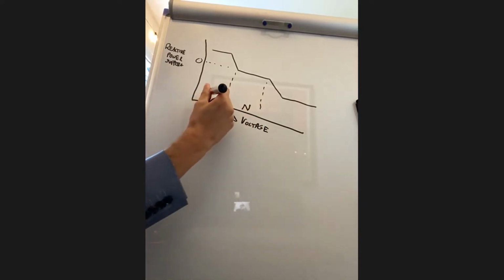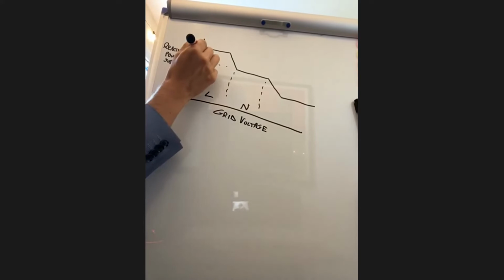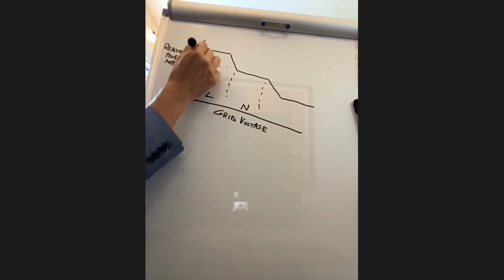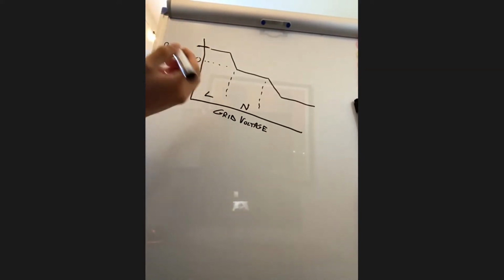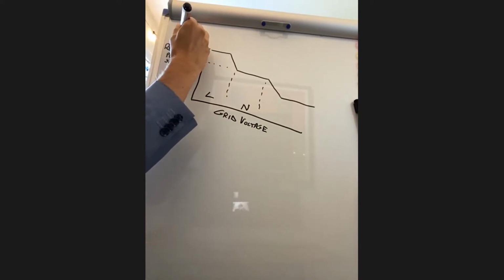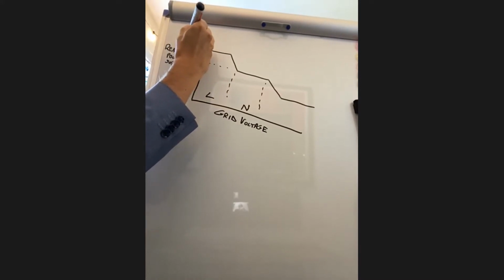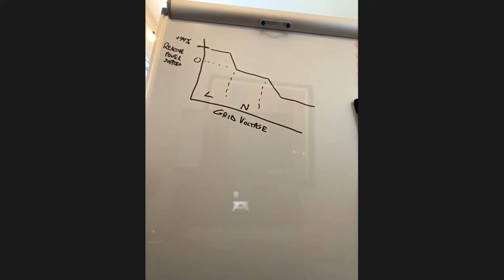However, when grid voltage is low, you could say, actually, now I do need you to give me some reactive power. So give me, let's say, plus 44%, and I can show you where that number comes from, but it's just a relatively common number that you might use in a volt var curve. So give me 44% of your nameplate capacity in the form of reactive power.